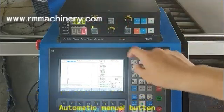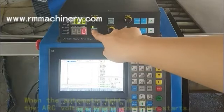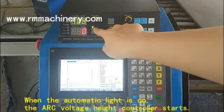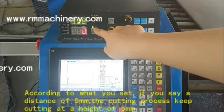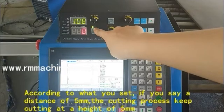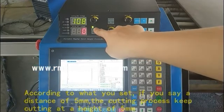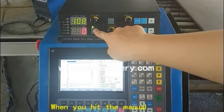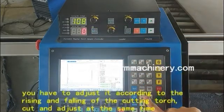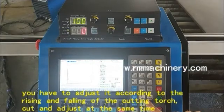Automatic manual button. When the automatic light is on, the ARC voltage height controller starts. According to what you set, if you say a distance of 5 mm, the cutting process keeps cutting at a height of 5 mm. When you hit the manual, you have to adjust it according to the rising and falling of the cutting torch, cut and adjust at the same time.